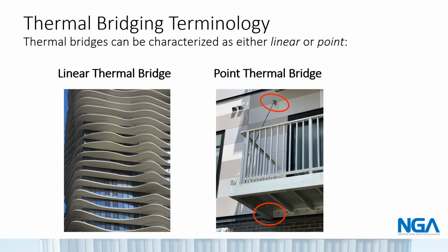In this example, steel balconies with a big beam are penetrating the insulation on the left and right edges of the deck, as well as at the location of the small plate connecting to the tie rod that is helping to suspend the deck.